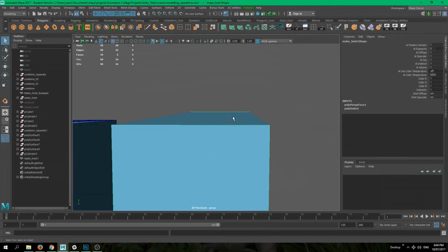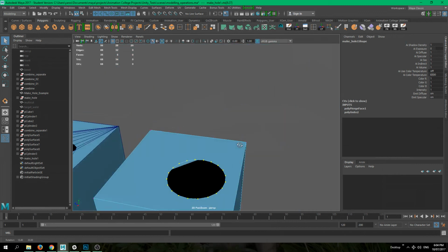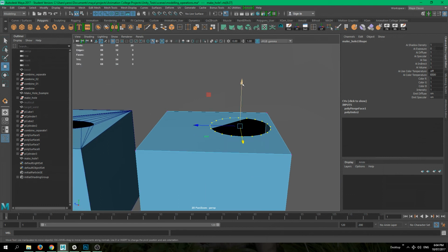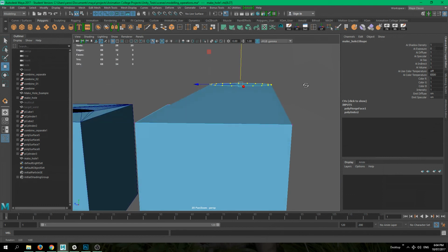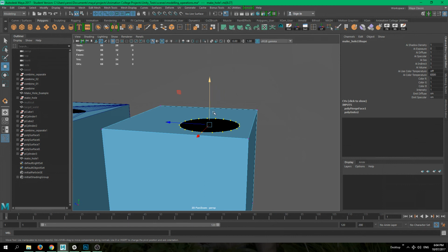And it doesn't look super great because, as you can see from this view, it's not sitting exactly on the same plane. So in order to fix this, if we go into our fix menu and just select our vertices that we just created on this face, what we can do is we can move them around and we can snap them on our y-axis. So I will be using V snapping again. Snap, and middle mouse click on this vertex over here, and it should snap it back.